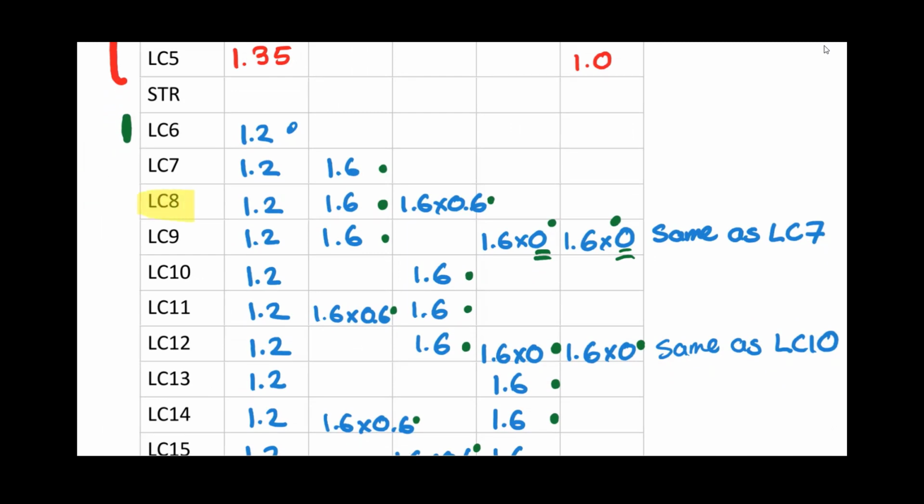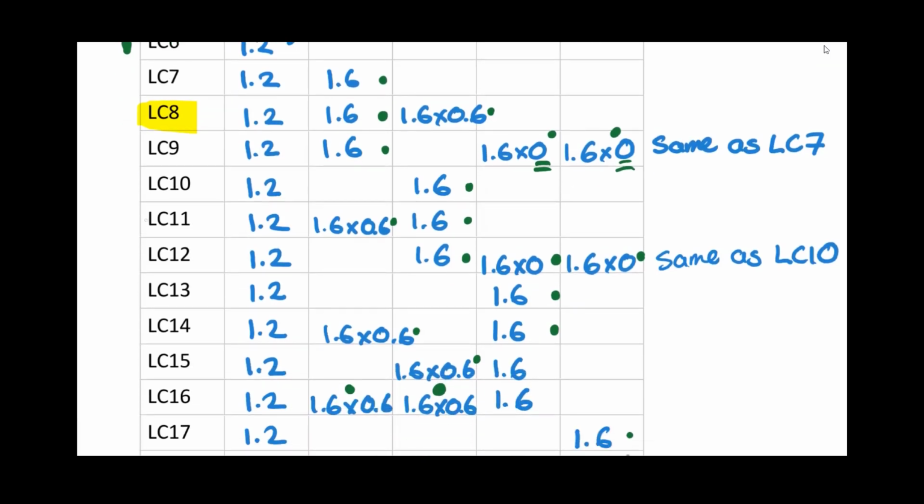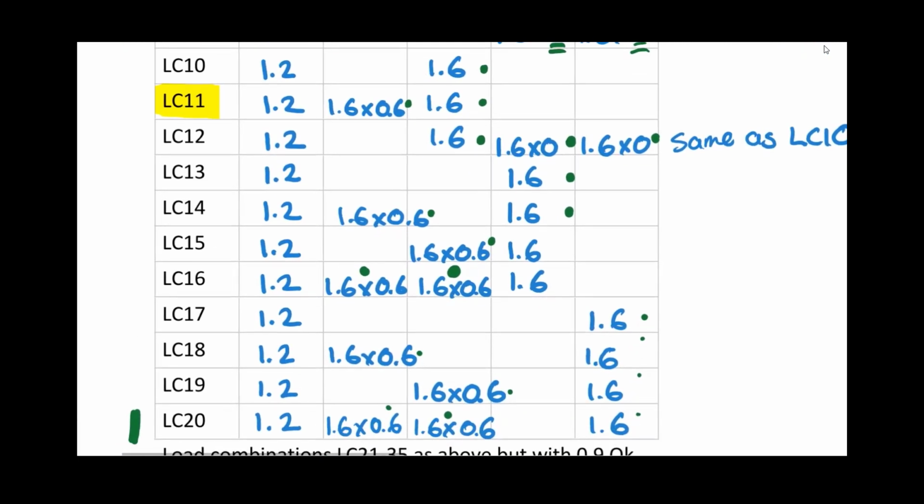Load combination 8, because that is the maximum amount of downward load. We'd need to then see which of the imposed loads would govern, but load combination 8 or 11 are very likely to govern. Those are 2 we'd probably very quickly go have a look at in terms of worst case.